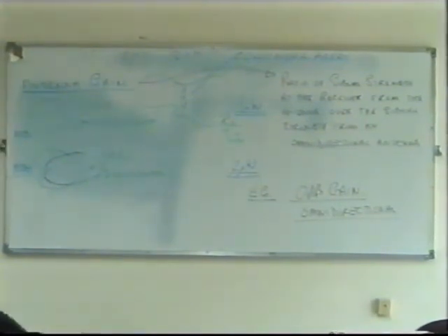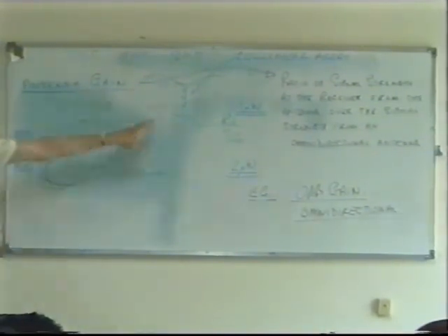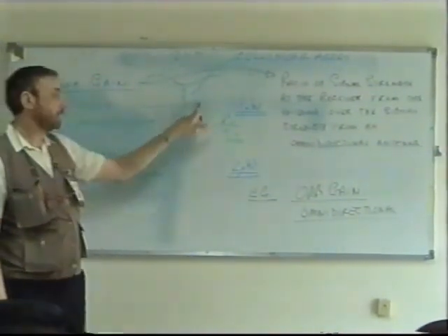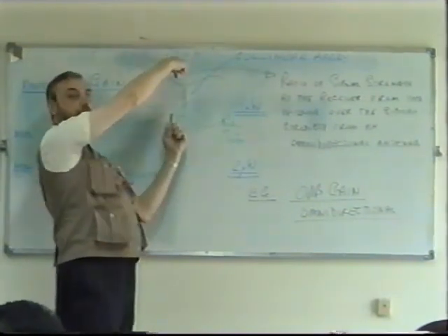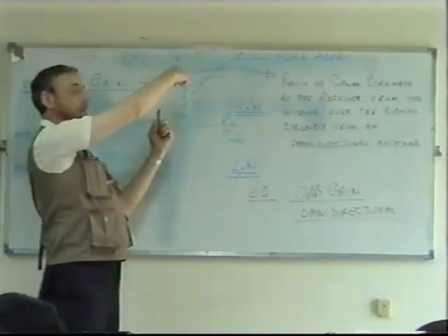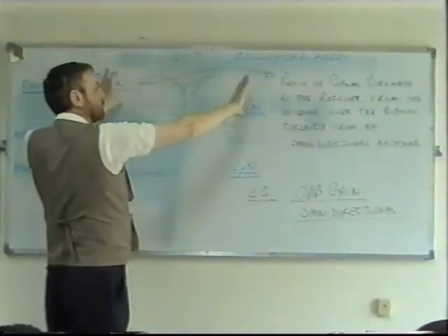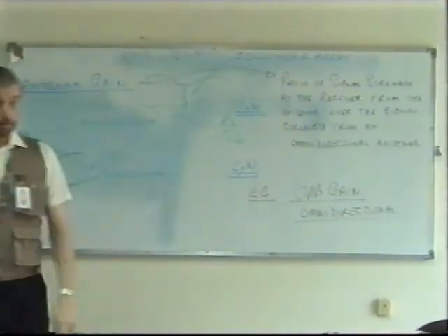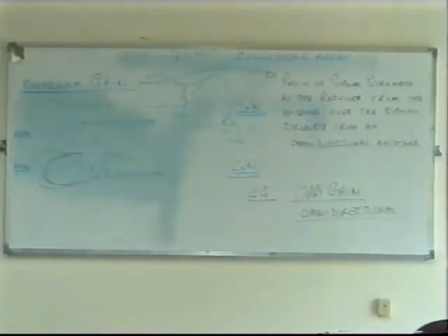But just because you transmit all the way round doesn't mean it's omnidirectional. Omnidirectional means all the way round, also at the top and the bottom, horizontal and vertical. Omnidirectional is like a balloon. But if you have a stacked array or collinear array, you cut out the top and the bottom radiation, and the energy that would be lost there now goes out to increase the signal at the sides, which is really how you want it. That's the most efficient for normal mobile.